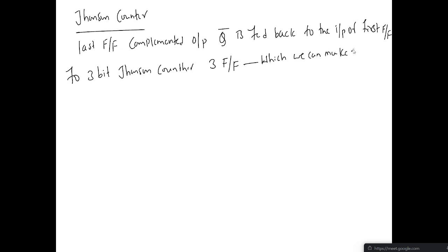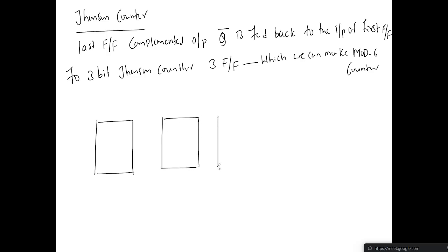Mod 6 counter. So how can we design it? You are using 3 D flip flops: D0, Q0, D1, Q1, D2, Q2, and this is Q2 bar.